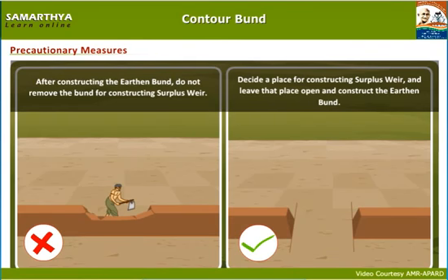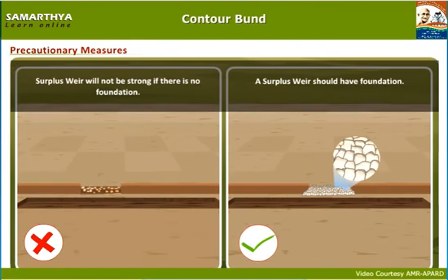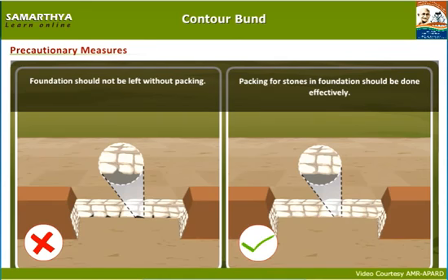Surplus weir will not be strong if there is no foundation. A surplus weir should have a foundation. Foundation should not be left without packing. Packing of stones in the foundation should be done effectively.